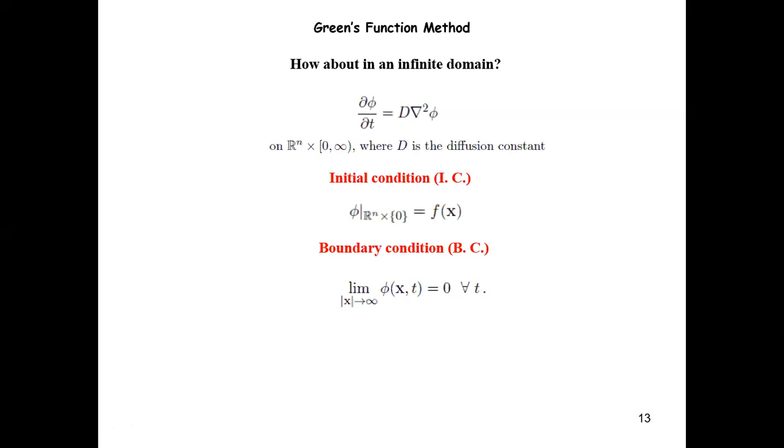This is mathematically understandable, and in reality it is also reasonable as long as the length of the bar is much larger than the typical diffusion distance for the solutes you have. For example, if the bar is 3 meters long and we look at carbon diffusion at room temperature, you can consider the bar effectively infinitely long compared to a single carbon atom. So this is quite reasonable.